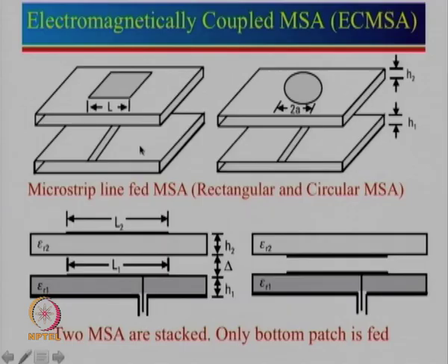And here, if we have an air gap, we can also use another substrate of low dielectric constant, so that the effective dielectric constant seen by the patch will be relatively small and the total height will be more, which would lead to a larger bandwidth.